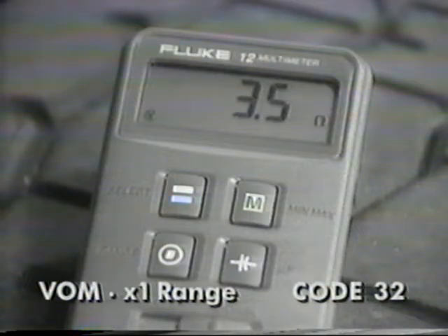So turn the key off and disconnect the connector at the defuel solenoid, and measure the resistance between the pins. A good reading for an electro-pneumatic solenoid is 13 to 18 ohms. The good reading for an electro-hydraulic solenoid is 2.5 to 4 ohms. If the readings are out of spec, replace the solenoid.